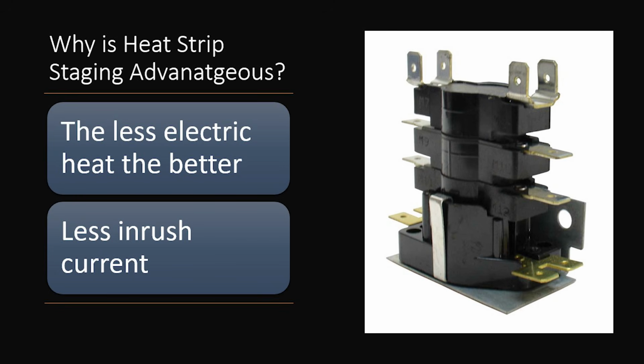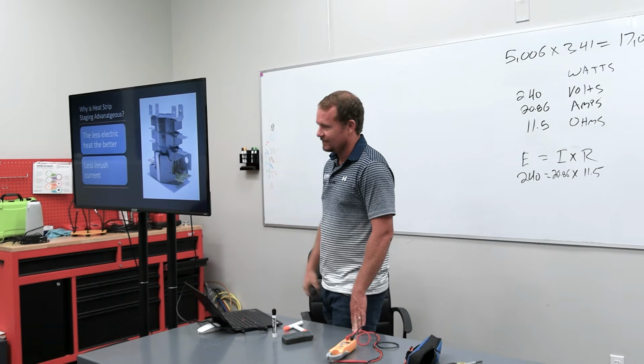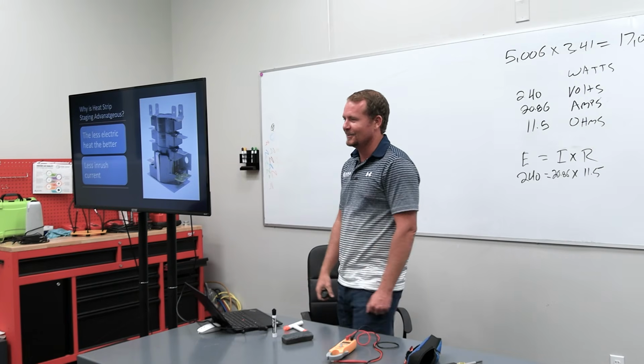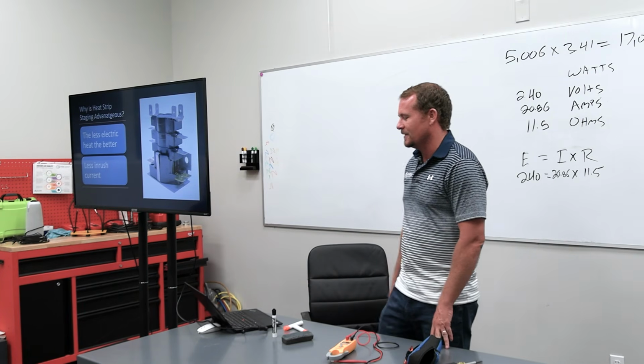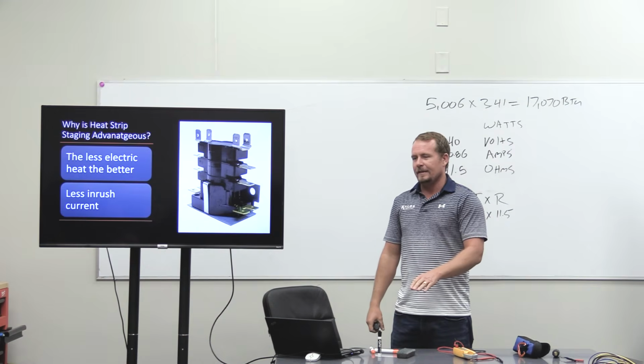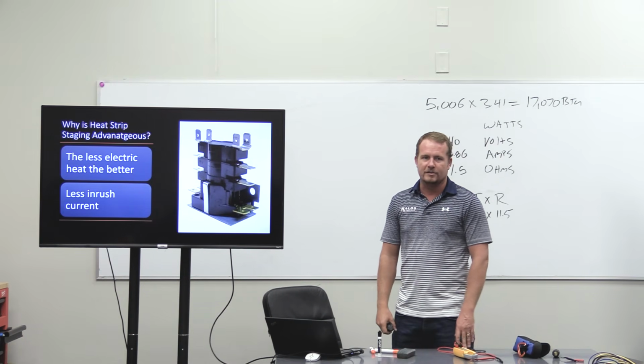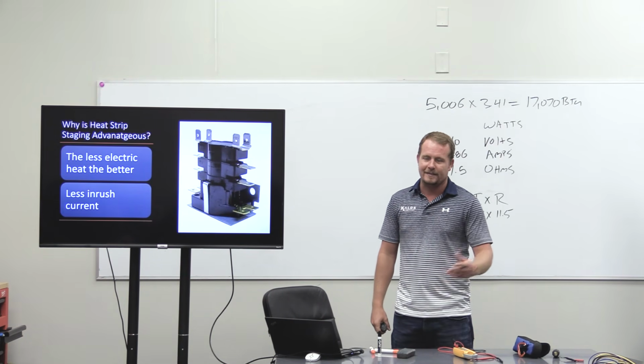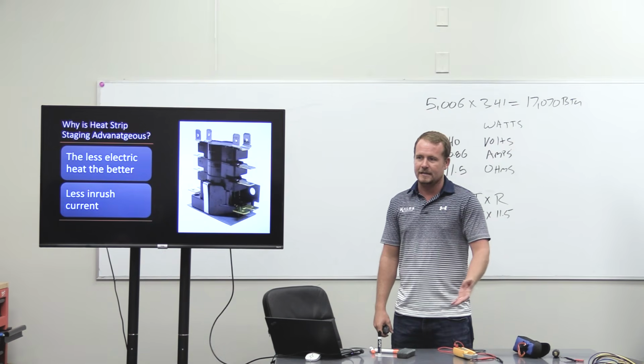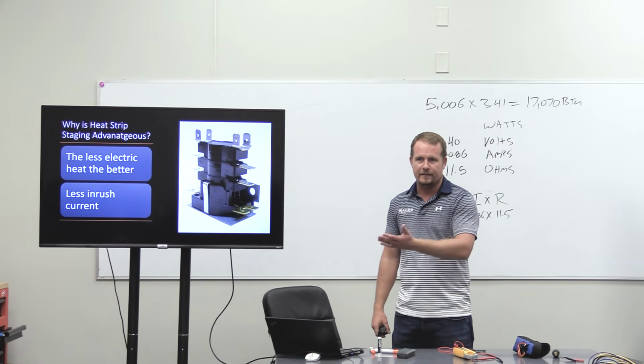What else? There's one other thing. The less electric heat, the better. Yeah, you make a good point. The less electric heat, the better. So if you only need 5 kilowatts in order to keep up, then only run 5 kilowatts and let the heat pump do the rest, right? Because the heat pump is far more efficient than the electric heat.